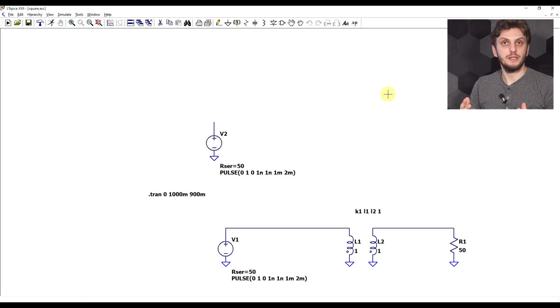and get the benefit not just of matching different impedances, but also getting galvanic isolation. Especially over long data transmission lines like Ethernet, you will see isolation transformers. And based on the cable impedance and the driver impedance, these can be one-to-one transformers or different ratios can be implemented. So we can again explore this behavior in a circuit simulator.